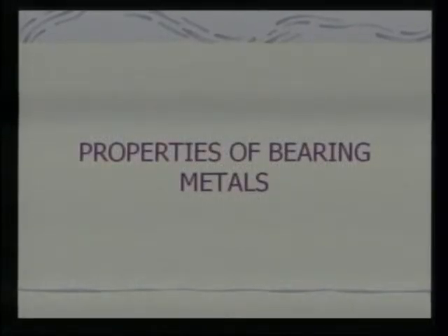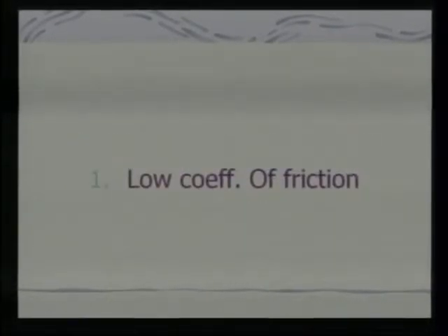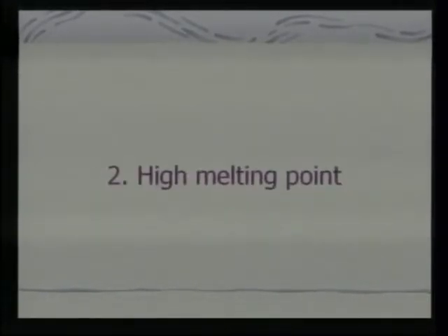Properties of the bearing metals are like this. It should have low coefficient of friction, that is very smooth surface to avoid frictional waste of power. High melting point, because the bearings are subjected to high temperatures. If it melts, it is going to fail.